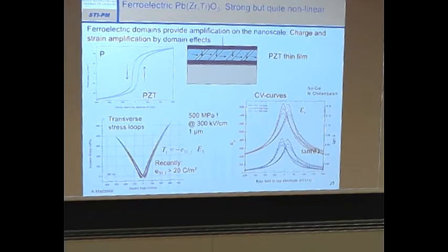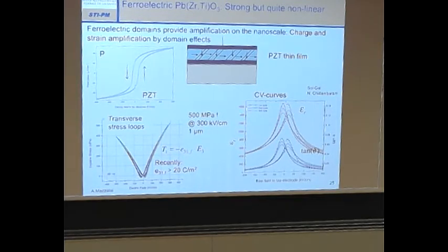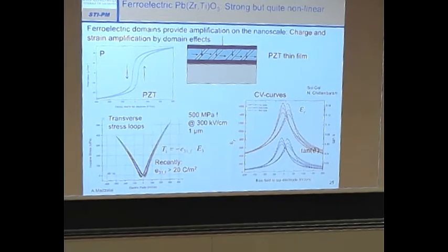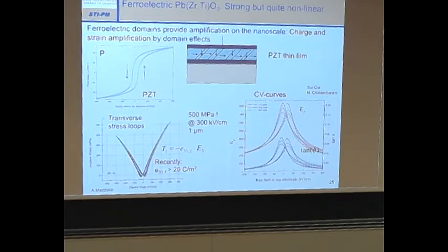When you measure the capacitance as a function of superimposed DC field, you know the capacitance is normally measured with a small signal, a small voltage excitation. So it's the small signal response to a small AC electric field, and you measure the charge that comes also as a sinus, and you calculate the capacitance. You can superimpose a DC field, so then you have a DC field plus the little AC excitation, and you see how the small signal response changes with applied DC. Here is a dielectric.